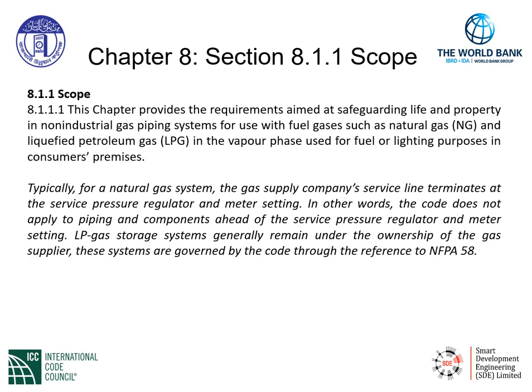Typically, for a natural gas system, the gas supply company's service line terminates at the service pressure regulator and meter setting. So what we're actually stating here is, in other words, the code does not apply to piping and components ahead of the service pressure regulator and meter setting.